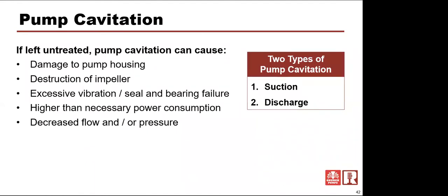So pump cavitation, as you saw in that video, is very damaging to the pump casing and pump impeller. I've seen areas where you could hardly even tell it was an impeller. The vanes are completely gone. It's basically a rotating disc that looks like it had severe erosion or chemical attack, but in fact, it's oftentimes cavitation. And one of the signs that you're going to see is that flow going through that pump is going to sound like you're pumping gravel.